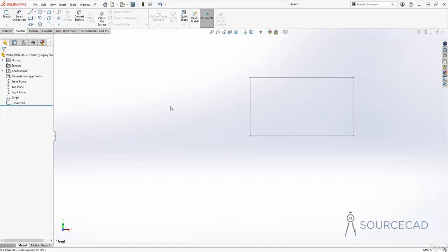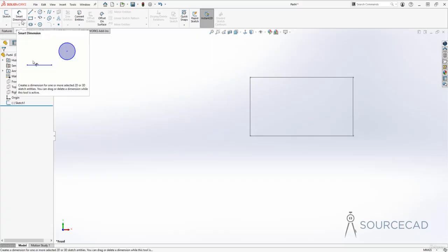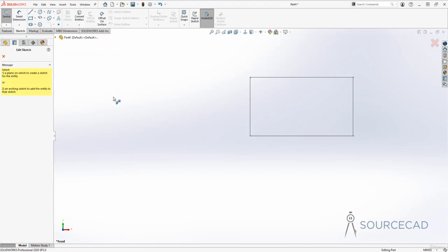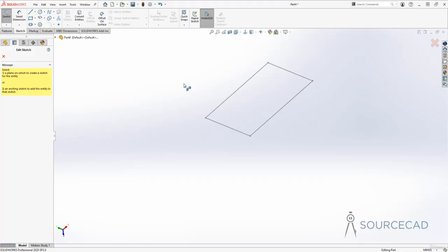Now let's do this one more time. But this time, instead of selecting a sketch, I will select a drawing object directly. So actually we have all of these drawing commands. I'll select the circle. And once again, it will prompt us for a plane. As you can see, planes are not highlighted here in the drawing area. So I'll just orbit my drawing slightly, but still the plane is not visible. In these kinds of situations, you can go to this feature tree and select a plane from here.